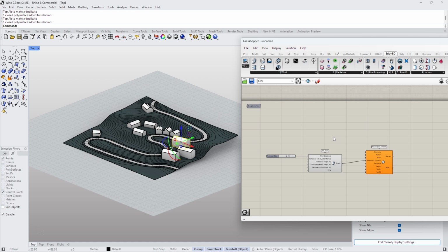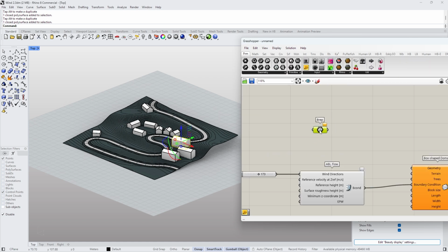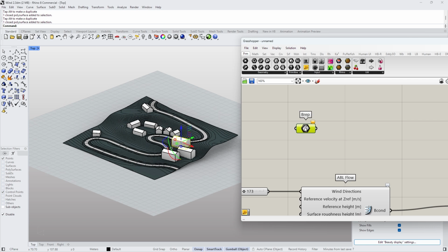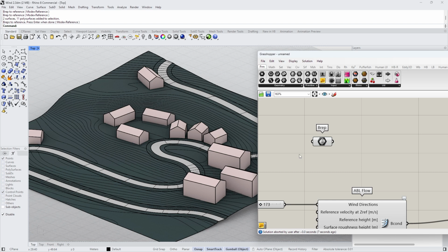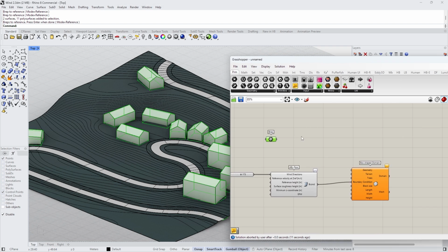Okay, so we can see a bit what it does. Okay, geometry. I think you can place B-wraps into here, but what I recommend is to translate everything into meshes. Let's do that first. So I will add my buildings first here. Oops, this is strange. Okay, I would translate everything into meshes. Mesh B-wrap. That's what I want.